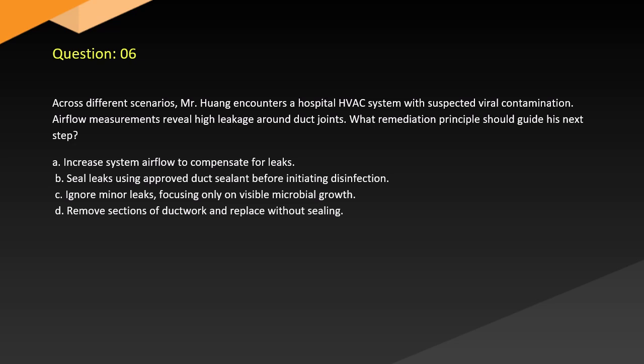A. Increase system airflow to compensate for leaks. B. Seal leaks using approved duct sealant before initiating disinfection. C. Ignore minor leaks, focusing only on visible microbial growth. D. Remove sections of ductwork and replace without sealing.